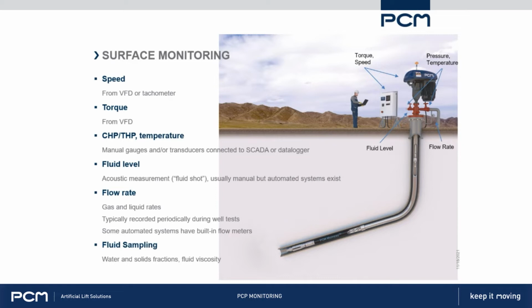Fluid sampling. What are the properties of the fluid, the densities, how much sand is in there, what's the viscosity of those fluids. That's not something you're measuring every day, certainly, but if you get an occasional measurement on that a couple times a year, maybe it would be good to know. For solids, you probably need to measure that a little more often if you're in a high solids application.